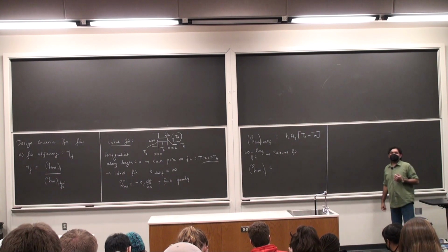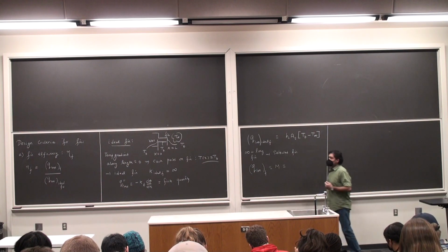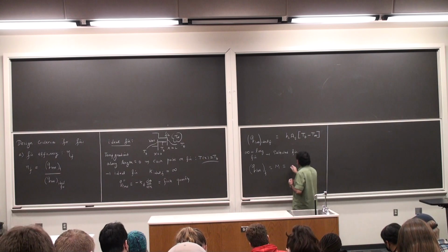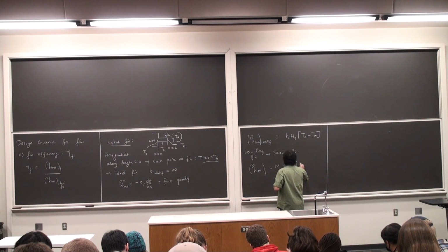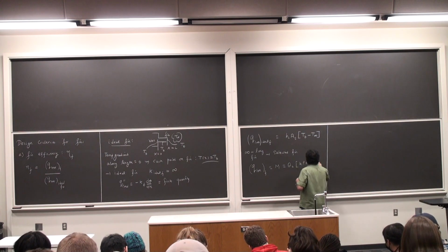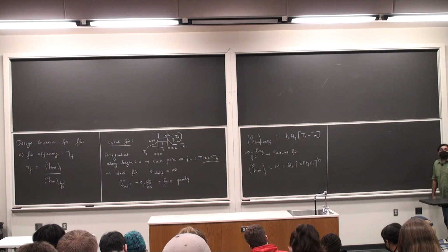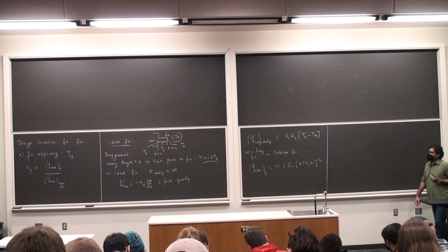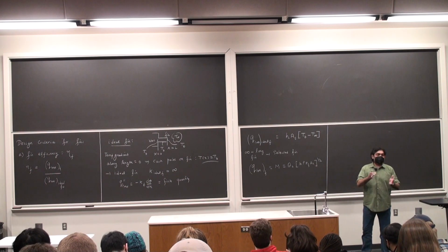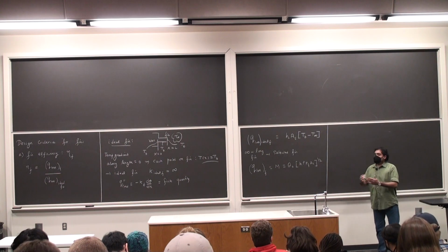This is equal to capital M, where capital M is defined as the following concoction of parameters: theta B, h P, Kf, thermal conductivity of the selected fin, area of cross section of the selected fin, the perimeter of the selected fin, the heat transfer coefficient on the ambient surroundings. Theta B is Tb minus T infinity.